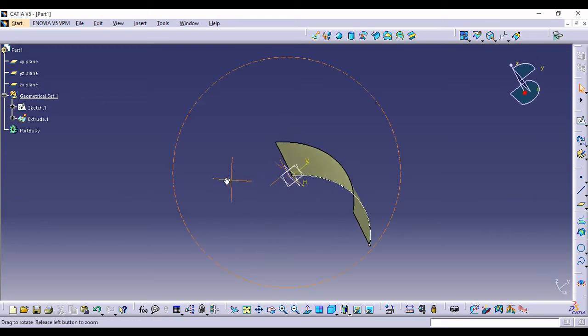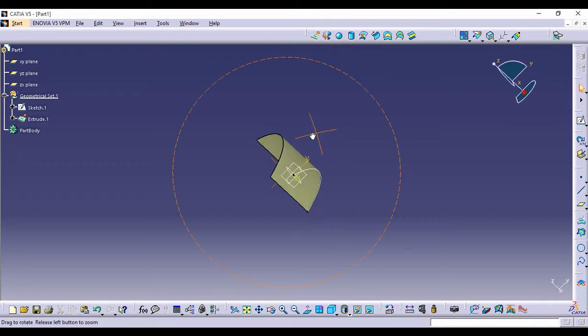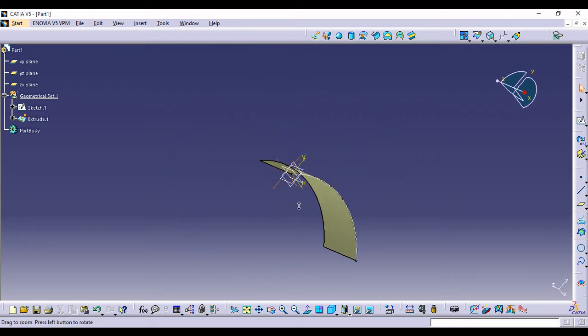Now this is simply a surfacing. If I compare this with the 3D model, in the 3D model I will get the entire thing as a solid one, but here I am getting a surface one. So that is the basic difference between 3D solid modeling and surfacing. The name itself indicates it: the model which we created in part modeling, that is 3D, is a solid, solid modeling, and here it is simply surfacing. So like this you can create any kind of shape, right? So this is simply the extrude one.